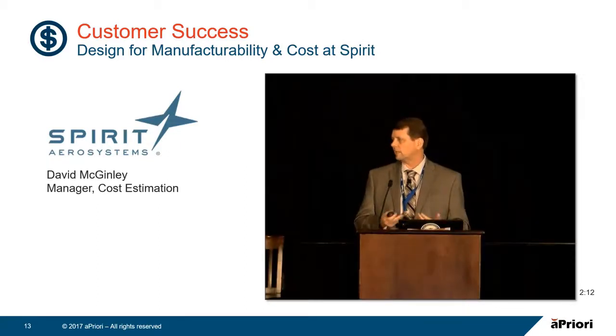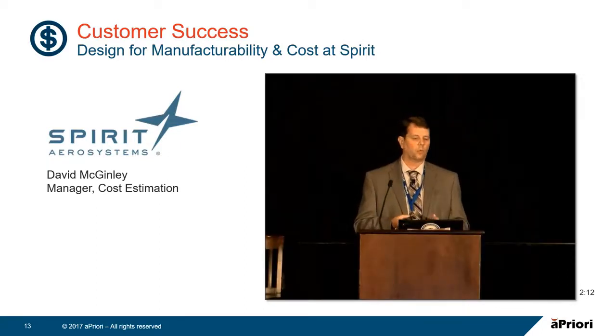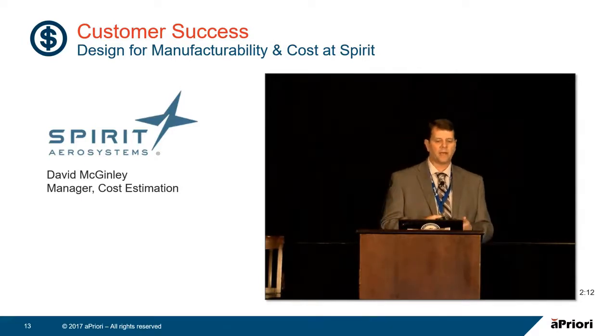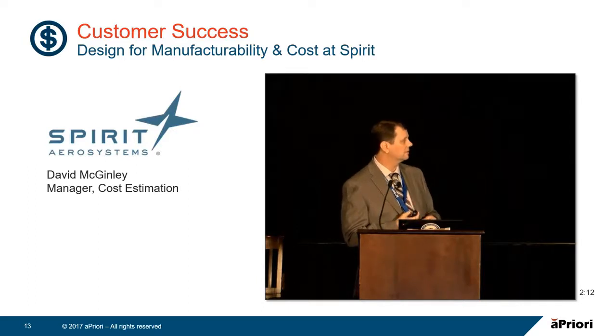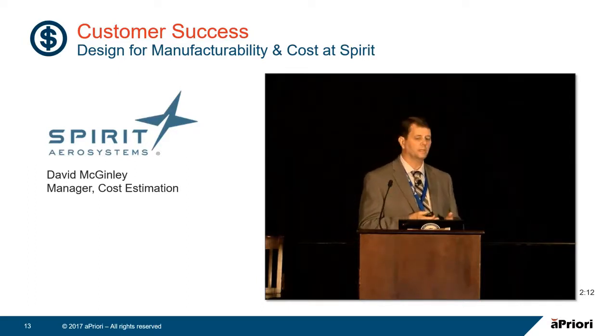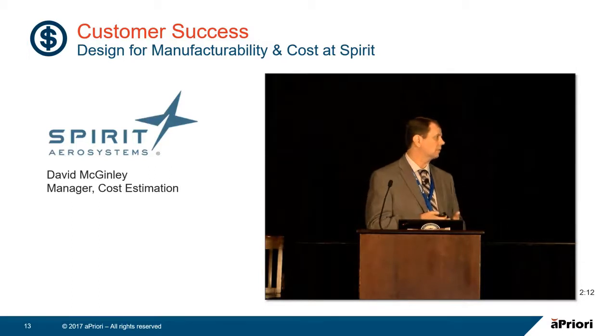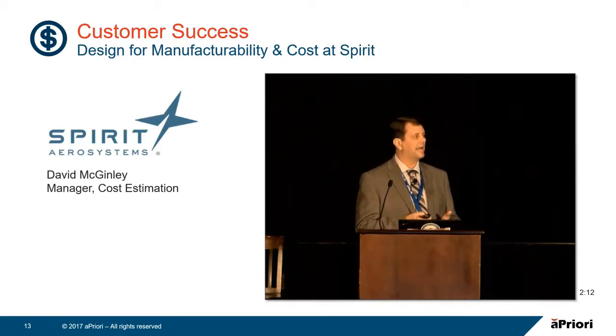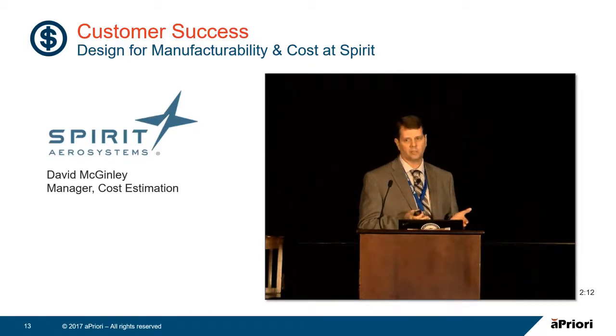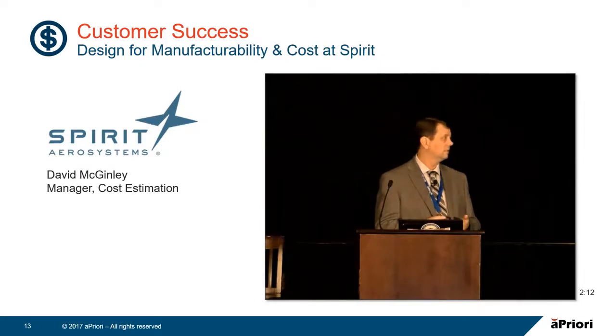So as we went through that, engaged in dialogue about requirements versus what looks nice and all this stuff, they came back with a revised model where they removed the radiuses and changed the fillets so it would accommodate a better cutter path, changed the contouring to some planar surfaces, and I think actually those paths are even gone today. There was some further discussion that took place about were they even necessary at all.